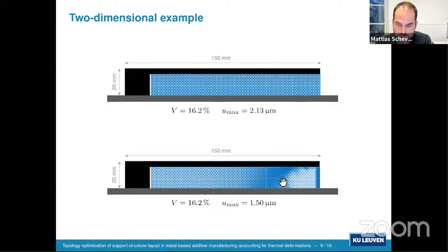And then we also observe larger bar diameters in this area here. And we think that this part acts as some kind of a shear wall that prevents shrinkage of the entire cantilever, as this shrinkage would lead to a movement to the left of this point, and so to bending of this strut. And this bending would lead to an elongation of the rightmost fiber of the strut, which would result in an upward displacement. And all that is prevented or restrained by this shear wall-like structure.